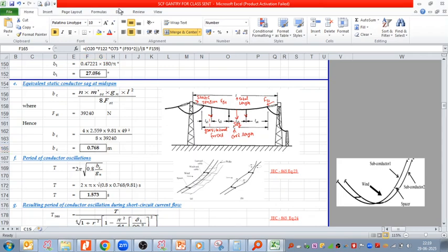Generally, for the FST value, if we work on an Indian project, we refer to the PGCIL standard, which Raghav sir discussed. But for the value you have taken, in abroad projects or any renewable projects which we work on in India, that is one challenge we face, to overcome those comments, like how can we directly put 4,000 for the quad conductor in that case.